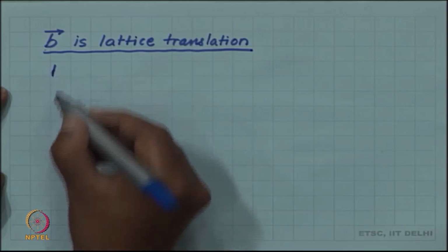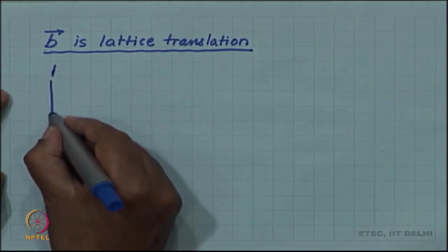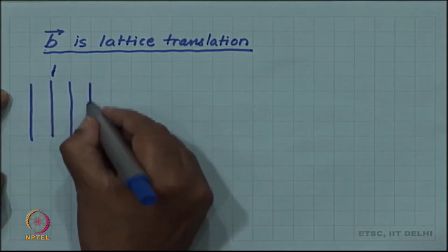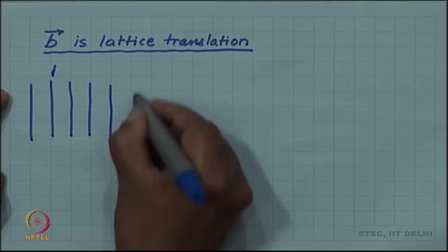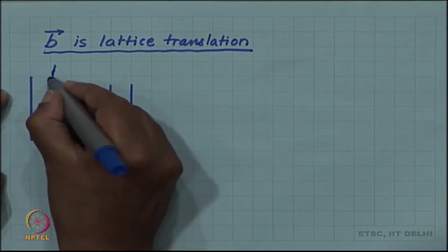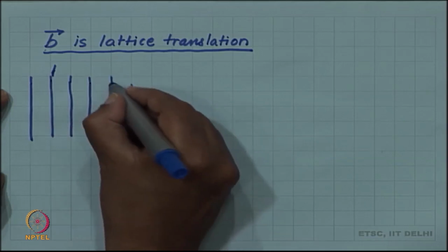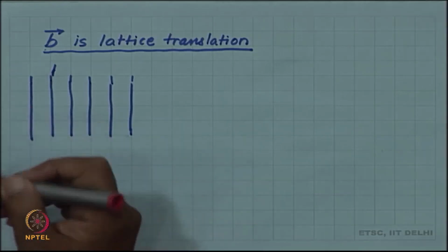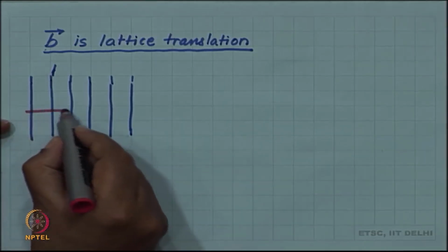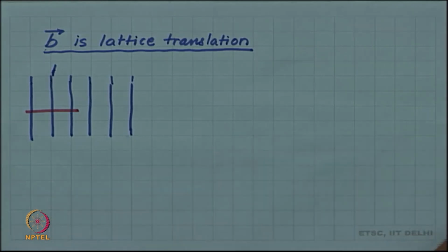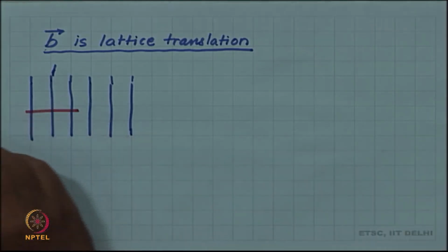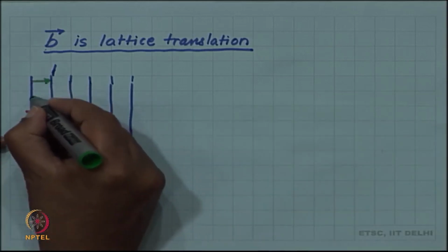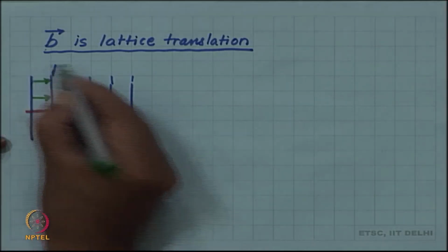This is based on the fact that, if we look at the model which we created for the dislocation line by cut and slip, we said that we will cut a few planes and then push the first plane above the slip plane, so that it joins the second plane.